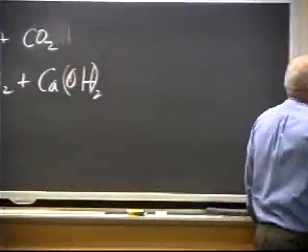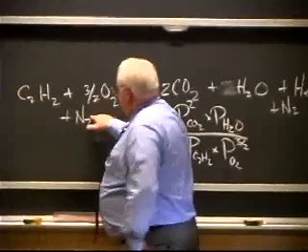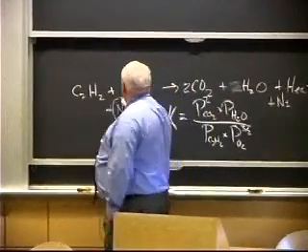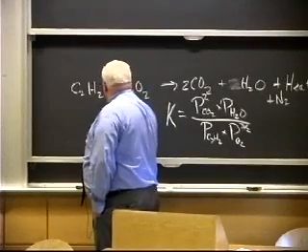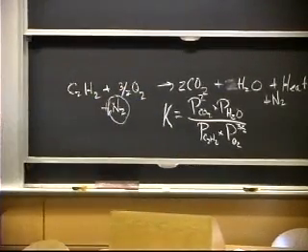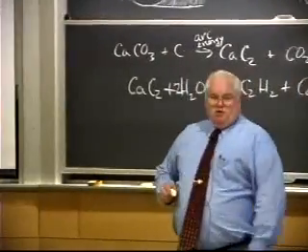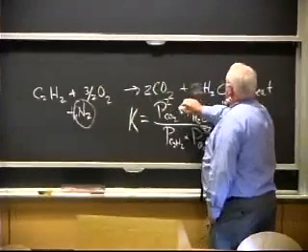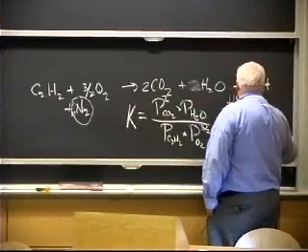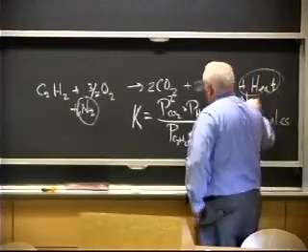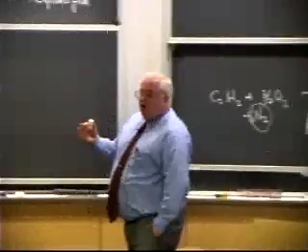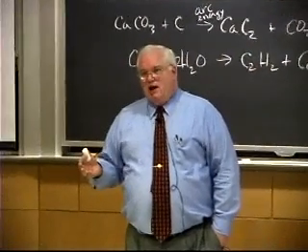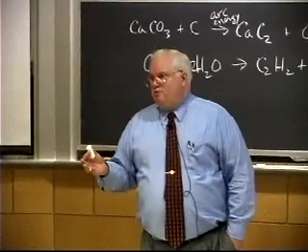Where do I have my inerts equation? Oh, here. With the nitrogen left over, if this is 3/2 moles of oxygen from the air, there's going to be 6 moles of nitrogen, a 4-to-1 ratio, right? So 6 moles of nitrogen over here, I end up with 2 moles, 1 mole, and 6 moles. I end up with 9 moles. And if it's the same amount of heat, I'm only going to get about 1/3 the temperature rise that I get if I have no nitrogen around, because I'm heating up 3 times as much gas: 9 moles as opposed to 3 moles.